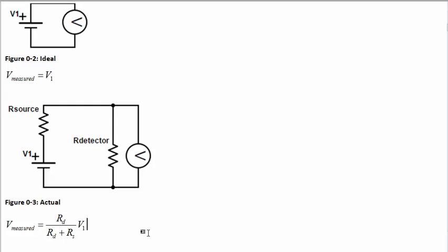If you've got a function generator that says that it's putting out 10 volts peak to peak, but has an output impedance listed as 50 ohms, then oftentimes it's actually putting out twice as much. It's putting out 20 volts peak to peak. What it means is that it would be 10 volts if you were to put it across something with an input impedance of 50 ohms as well.